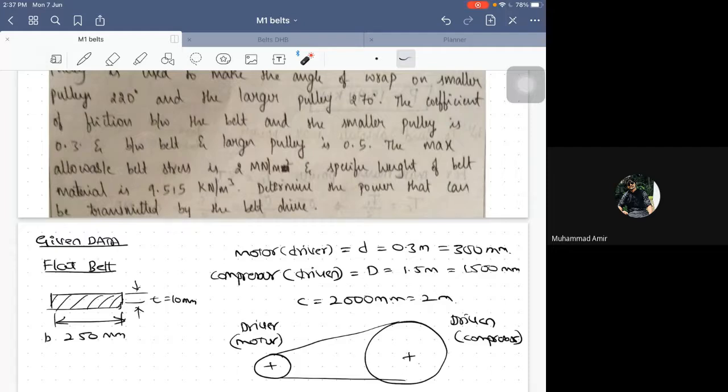See, look at the tensions in the belt now. So this is the tight side and this is the slack side. Look at the tension, how it is there. So what is the angle of wrap now? From here to here, this is the angle of wrap, whatever we are achieving now. So in order to increase the tension of the belt, in order to increase the angle of the wrap, what I do is I introduce a jockey pulley.